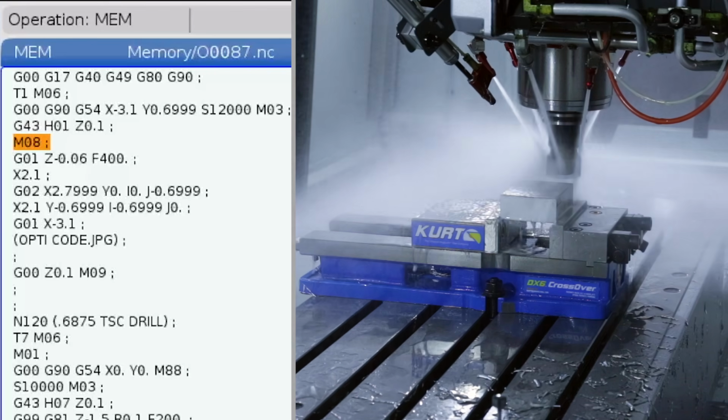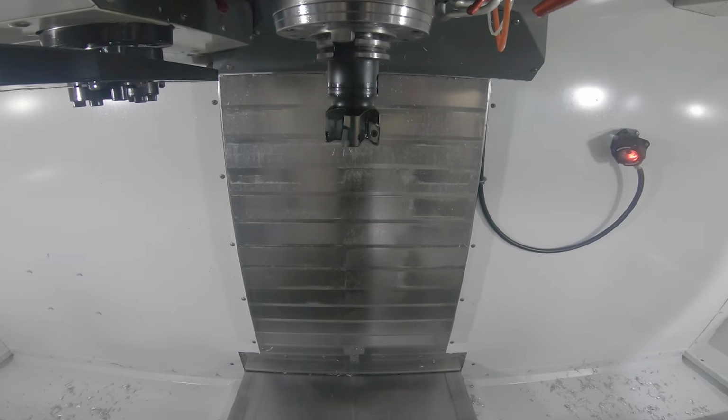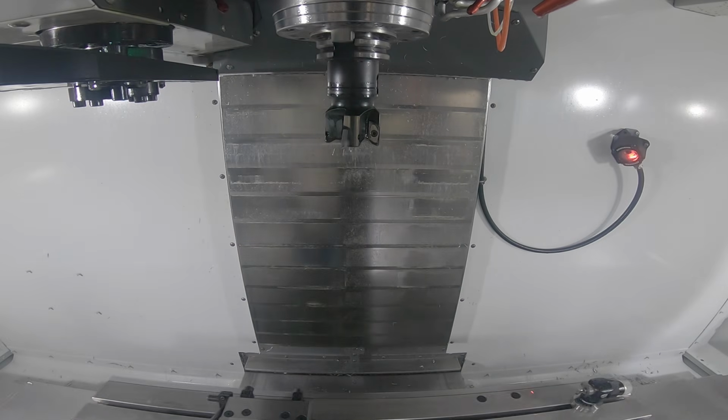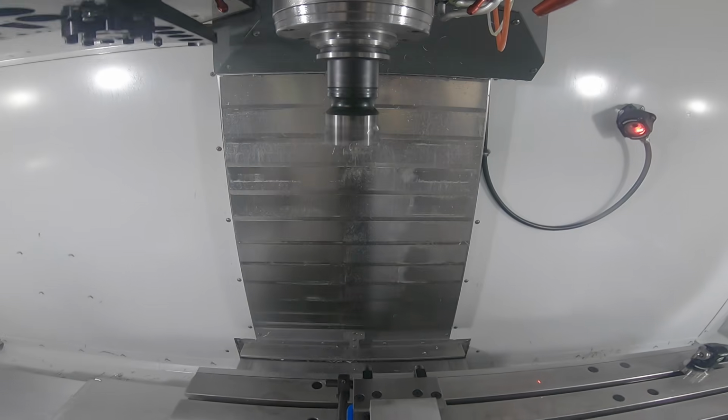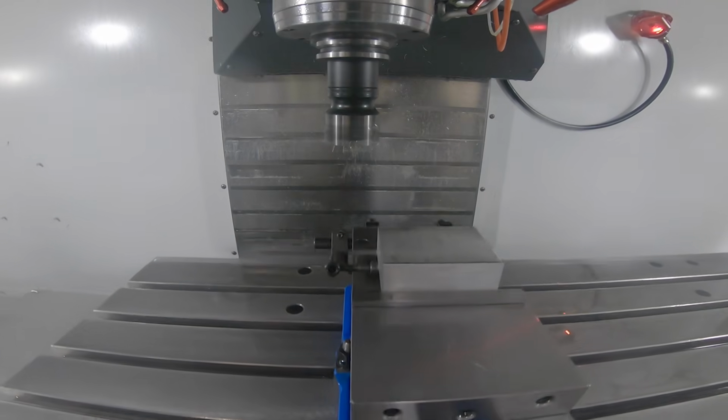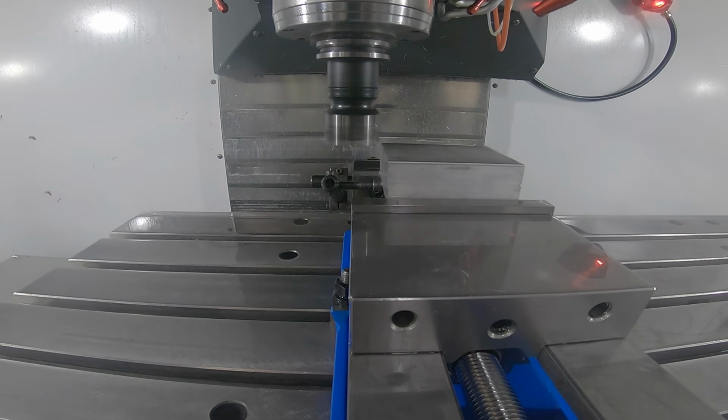There's a lot happening on these lines, but basically we're telling the machine to move quickly, turn on the spindle, use a tool offset. The tool offset is H1, move the Z-axis down to just above the part, and turn on the coolant.